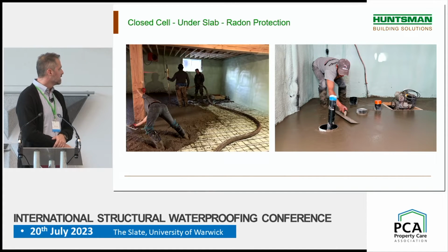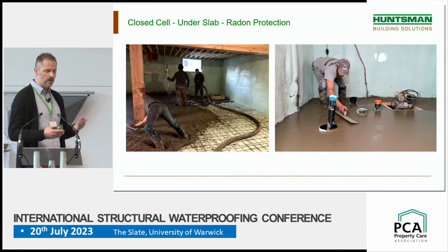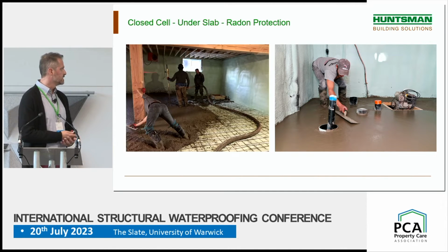So mechanical damage, as I was saying, spray foam resists well to mechanical damage and puncture. As you can see, when workers are pouring the concrete with their boots, with the shovel to lay down the concrete, thinner membrane can easily be punctured. As opposed to spray foam insulation, where you have 2 inches of product, so it's much harder to puncture than other systems.